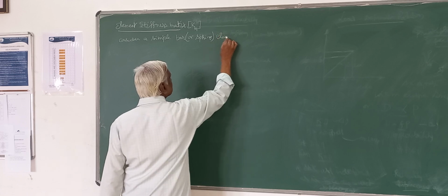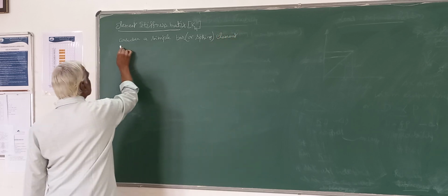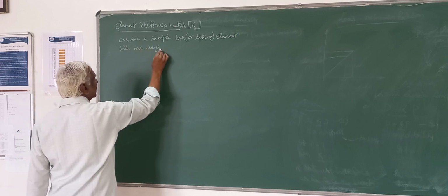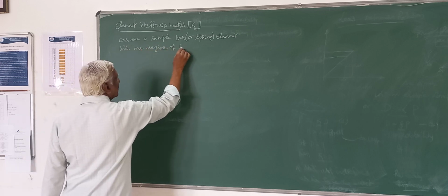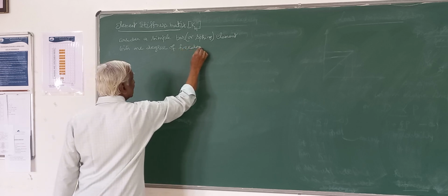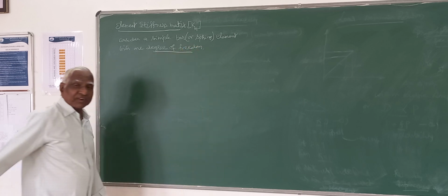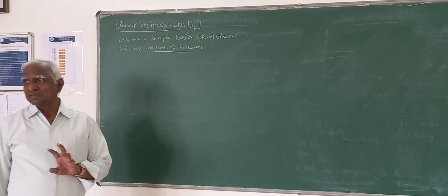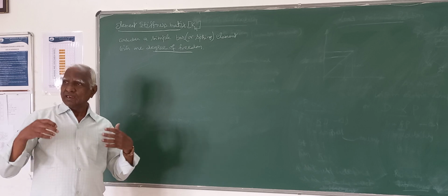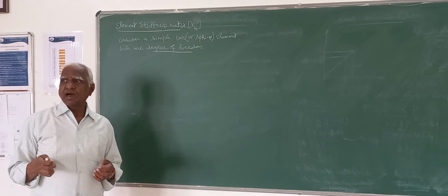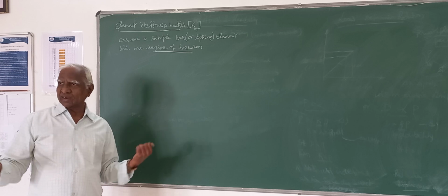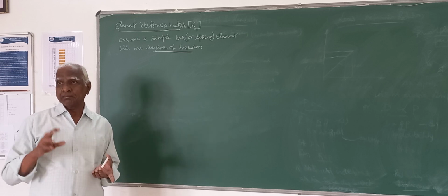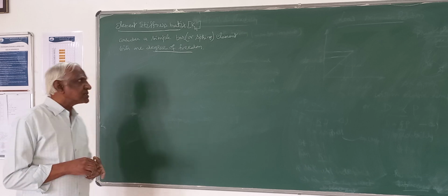Element with 1 degree of freedom. So this I have already defined. Degree of freedom always means kinematic indeterminacy. Whatever the type of displacements occurring at the ends of the members, we define degrees of freedom as the number of independent displacements.